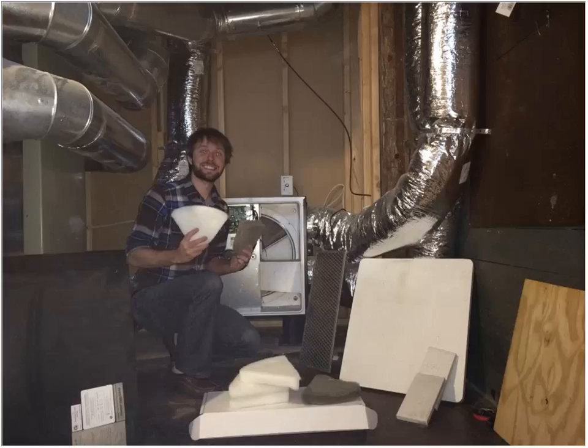This energy recovery ventilator will be constantly pulling in air and constantly exhausting air in two different areas, so not necessarily like a mouth breathing. What these do is they retain the indoor temperature. In this one, you've got a wheel that does it. In other ones, you've got some sort of substrate that transfers energy, so that you're capturing 75% to, depending on the unit, 99% of the wasted heat in the winter or the wasted cooling in the summer, and bringing it back in the house and only exhausting the stale air.